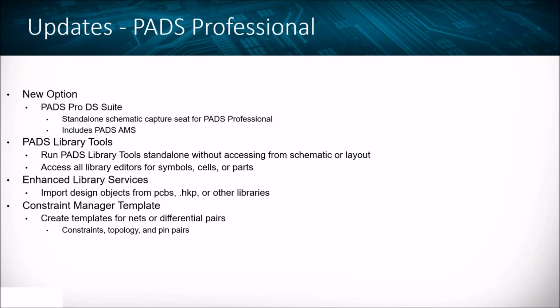A new feature to PADS Professional is the ability to run a standalone Library Manager instance. That allows us to open up an LMC or central library directly from this standalone library tool. In the older versions of PADS Professional, you had to access the library tool either from the schematic or from the layout. This will allow us to go into the start menu and just start a Library Manager instance and either create a new central library or open up an existing library, and start editing parts, symbols, or cells directly from there.